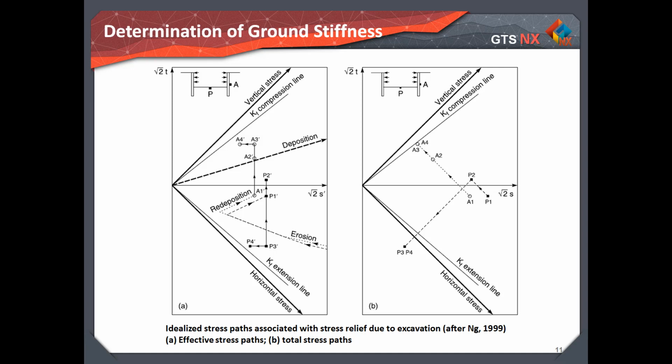As the mechanical behavior of soils depends on the current effective stress state and stress history, it may be important to obtain soil stiffness estimates from tests which follow a stress path compatible with that experienced by the soil at the particular site. He discusses this problem, and his approach is shown in this figure.